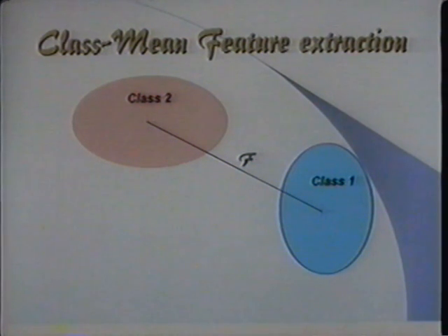Now, what you would like to do is include variables as inputs that will make a difference. For example, if I have a power system with a transmission line, and I have a fault on the transmission line, probably the flow in that line before the fault is very important in determining the security status. If the line is lightly loaded, then the system might be secure.